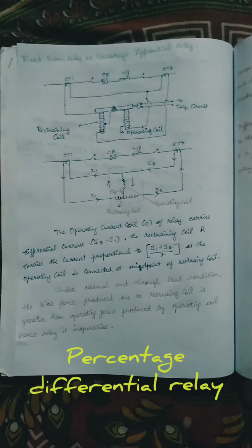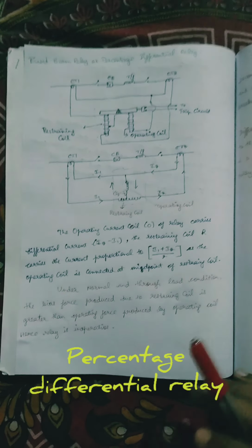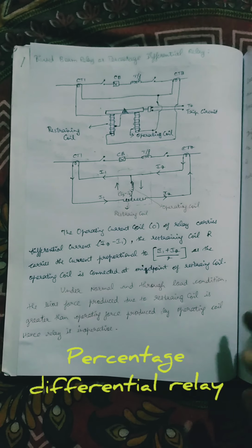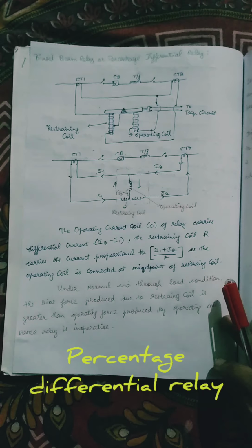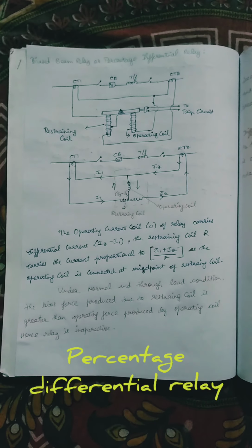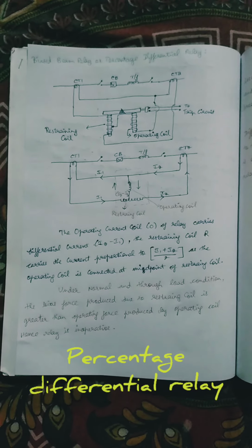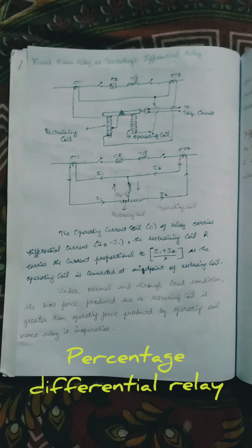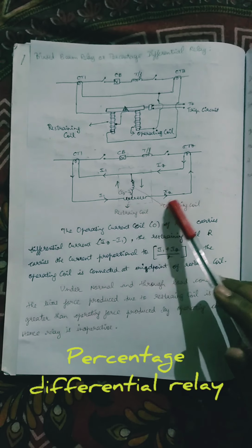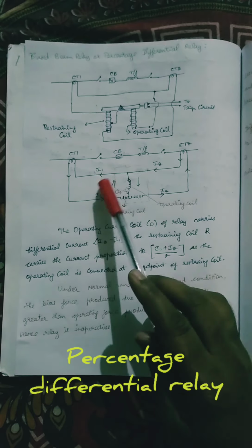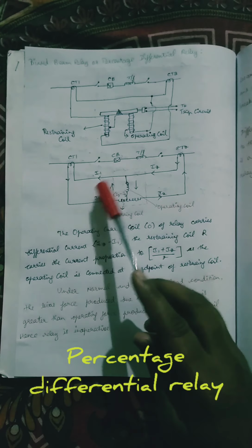Here the main thing is that the incoming and outgoing currents should be at the same level, or else within a minimum level for alarm or tripping. So there will be no false tripping, and no transient tripping either. That is what we are mainly focusing on. Then the CT ratios may be in the same ratio level, or they may be in a different ratio level also.